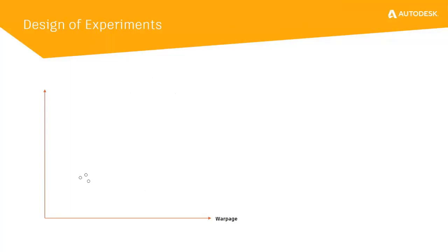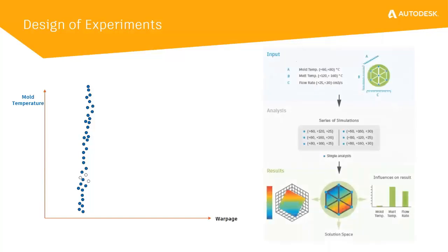Typically, simulations in Moldflow are run at one set of process conditions. Then one or two settings might be tweaked to understand how fill rate or pack pressure, for example, might affect certain results. The Design of Experiments tool is intended to disrupt that behavior and allow the Moldflow user to easily investigate multiple variables and their impact on the most critical results. We recognize that setting up a Design of Experiments analysis needed to be simple, and there needed to be a simple way to review the large amount of data in order for it to be useful.